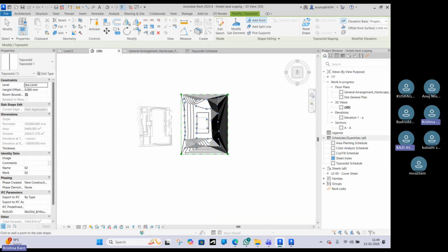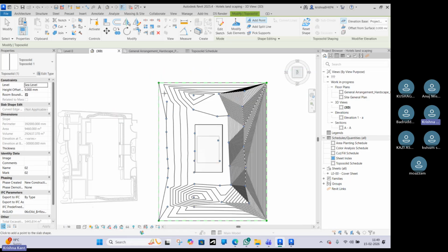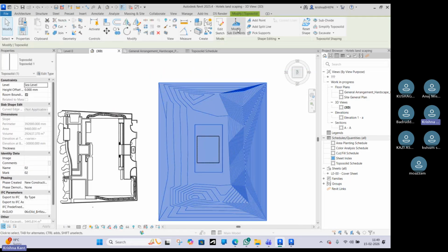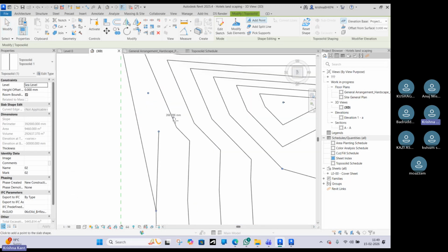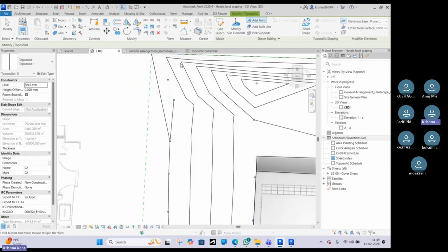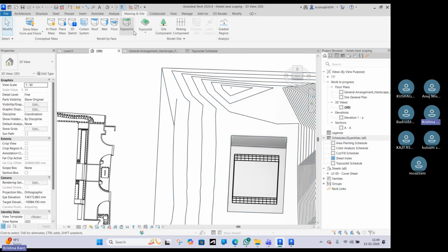Like generally the contour line is provided from the CAD. So if the CAD, like the surveyor drawings, if we get the contour lines, we have to add point exactly on the contour line one by one. Okay. And from the CAD we can directly create from the model. Like when you are drawing the topo solid, right now I have used the create from the sketch. But when the surveyor have given the CAD data, basically having the contours, directly we can use the contour line, so that time it is easier inside the project.